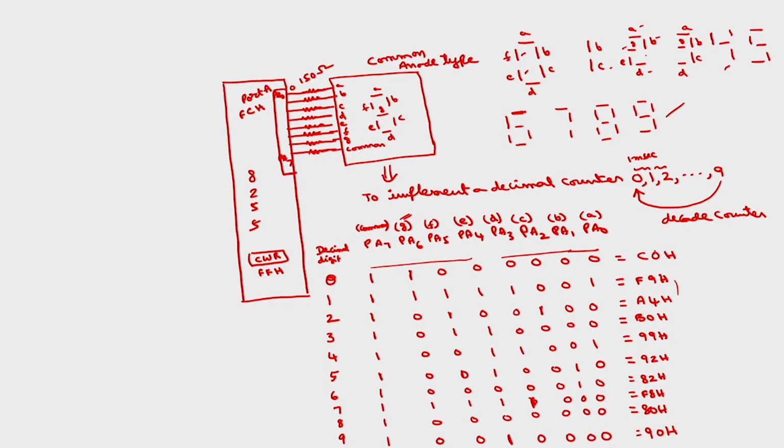So, I am going to store these values into some memory location starting with some offset, say 6000 offset, in a data segment whose starting address is say 50,000.